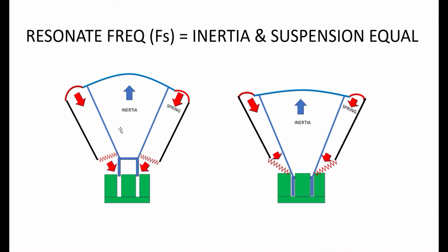It's at the position where it's easiest for the cone to move up and down and oscillate, right? It's a little bit like having a swing that is moving along at just the right pace, so that you just need to give it a tiny little push and it will keep going. And it's the same when a speaker is at its resonant frequency. You don't need very much power from the driver motor to keep the cone in movement, because it's at its resonant frequency and it wants to oscillate naturally, right? So that's what the FS is.